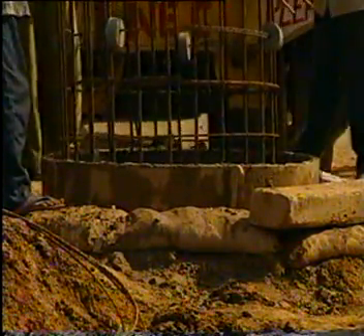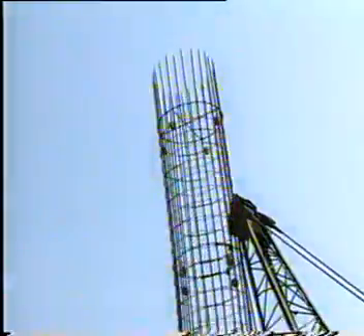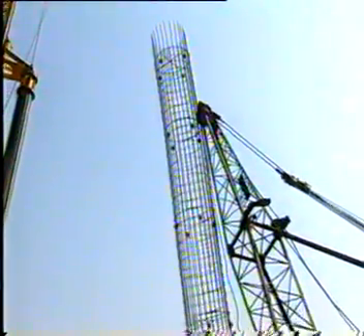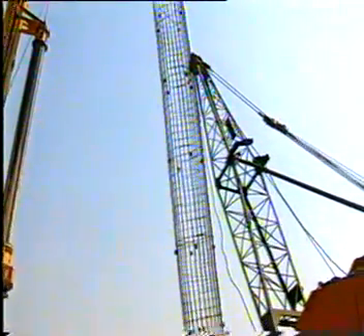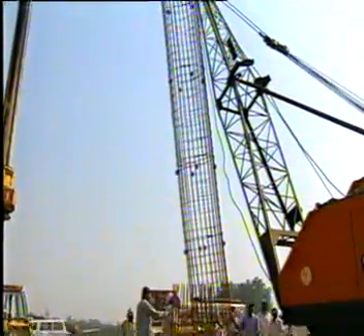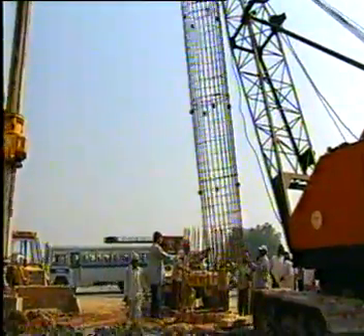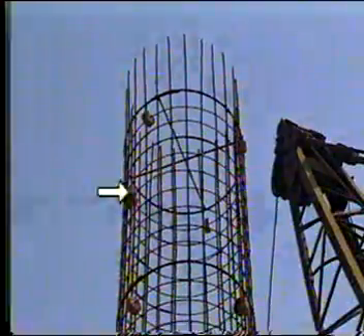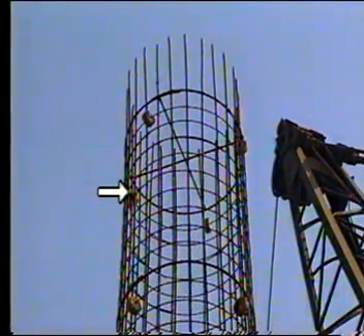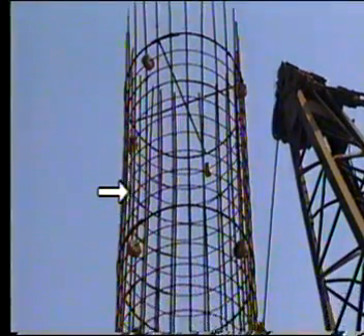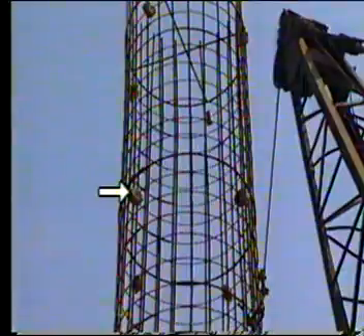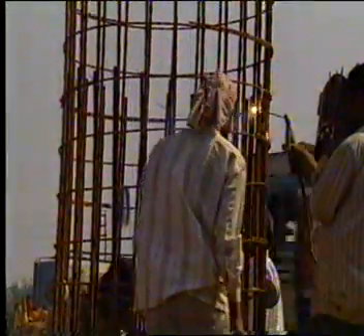If the length of the borehole exceeds 10 to 12 meters, then the reinforcement cage is made in two parts. The second part of the cage is welded to the lower part in position. Cement concrete blocks are provided on the outside of the outer reinforcement of the cage at intervals to maintain proper concrete cover.